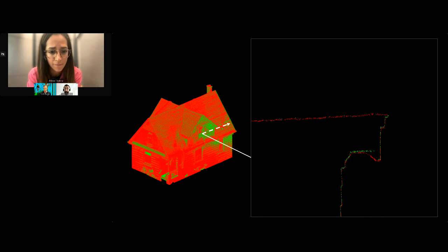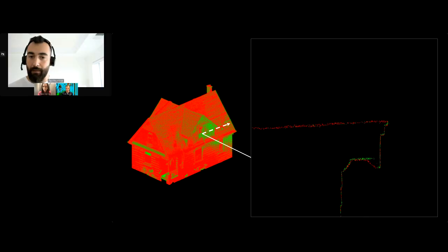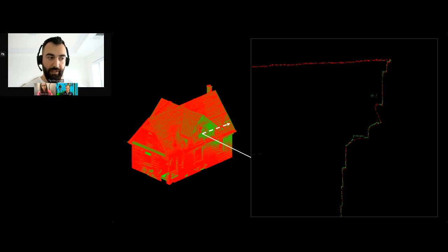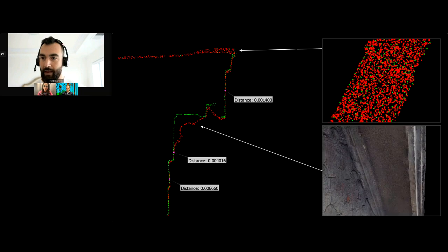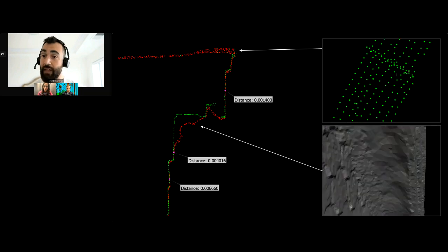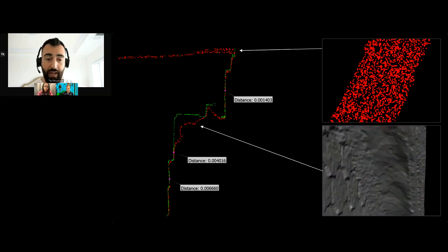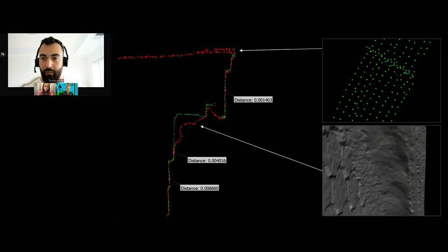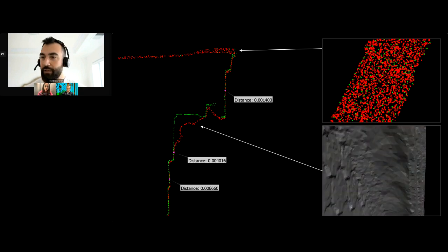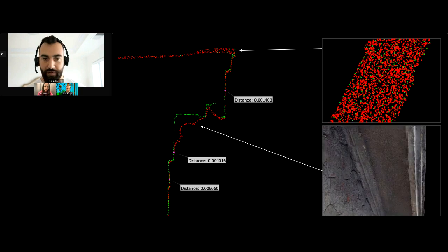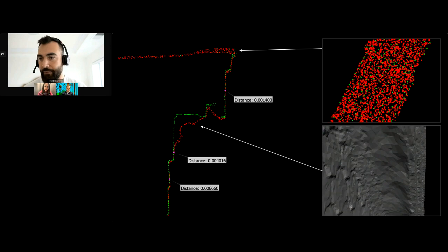Well, if I want to take both and create that hybrid scan, I prefer RealityCapture because it supports structured point clouds in a way that allows me to very finely tune that alignment between the photos and the laser scan. But generally, it's what you're comfortable with and what you're doing. So with photogrammetry, you have lots of options. With laser scanning, you use the software that that scanner supports essentially. At the end of the day, again, it's always what are you after?